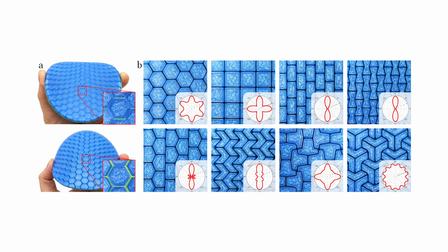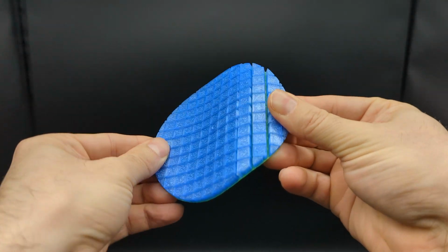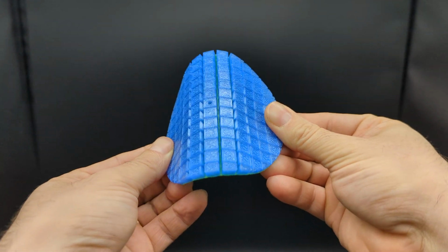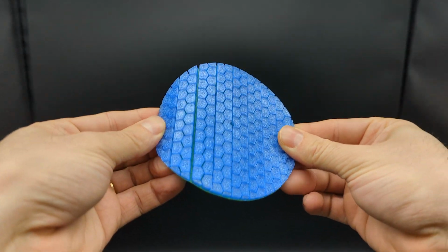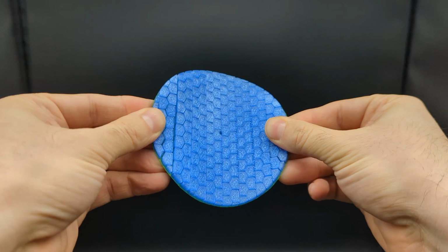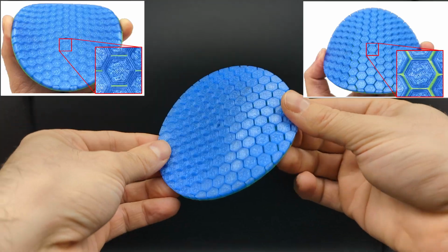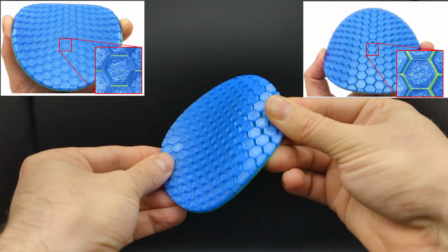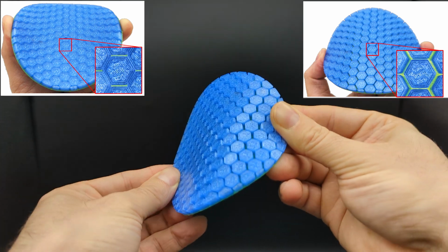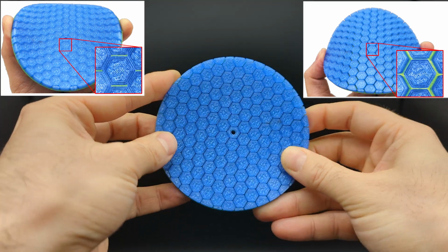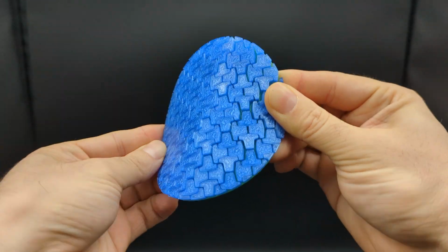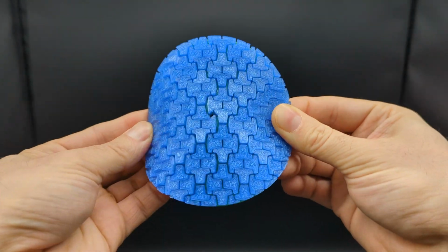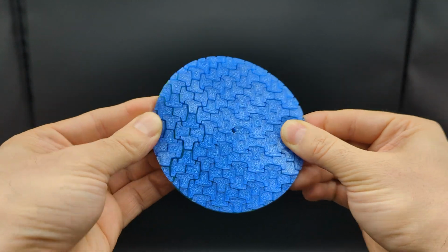In this work, we present a computational approach for modeling the mechanical behavior of flexible scaled sheet materials, 3D printed hard scales embedded in a soft substrate. The curvature response of scaled sheet materials is highly complex. While they show little resistance to bending for small curvatures, larger curvatures induce contact between scales, which rapidly increases bending stiffness. Moreover, their asymmetric structure in the thickness direction leads to distinct bending responses for positive and negative curvatures. Each of these effects depends in non-trivial ways on scale shape and arrangement, making it challenging to predict the mechanical properties of a given pattern.